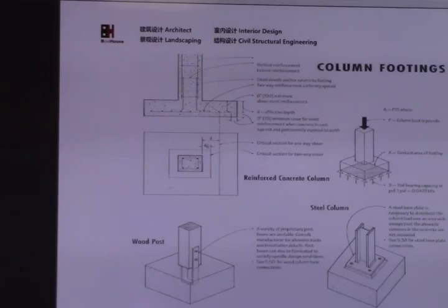If we need to put some columns in the middle of some beam, they don't need the strip footing, just use the pad footing. Yeah. This is the pad footing for the steel column. This is for the wood, for the porch. This is for the concrete.